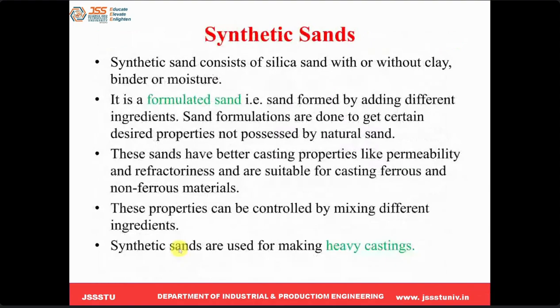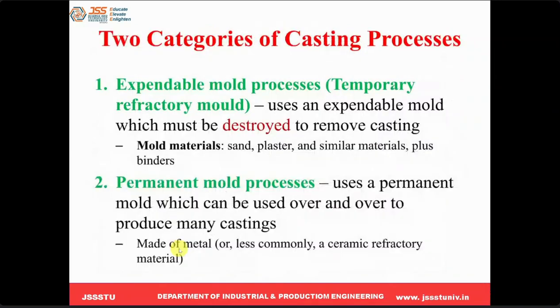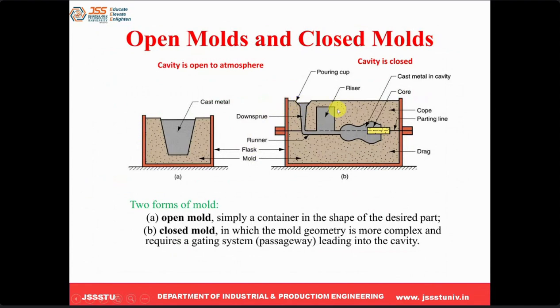I think I should have said this here. So okay, tell me quickly, what is the use of the riser? Before the riser, first, what is the pouring cup used for? It is called the sprue. To pour the metal into the cavity. Yes, the sprue is where the cup is connected to the runner. So that is where the metal is poured, and it allows the metal to flow from the pouring cup to the runner.